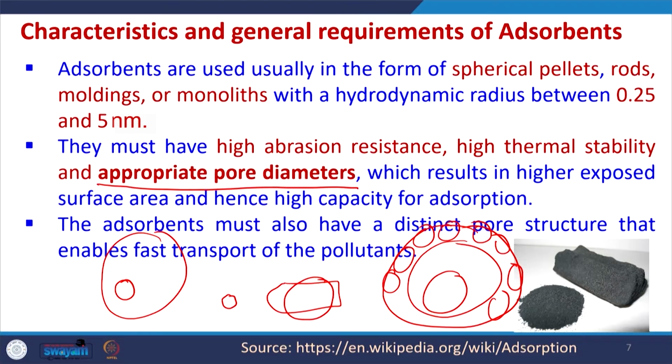That means if there is a kinetic regime which is controlling this pore diffusion, then overall it will take a lot of time for adsorption to occur, and the system may become very huge for the same separation. So, these aspects we are going to discuss more later.